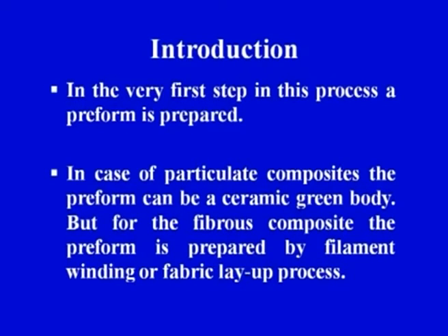But for fibrous composites, with continuous fiber, the preform is prepared by filament winding or fabric layup process. This highlights the fabrication of a preform before the processing of a ceramic matrix composite.